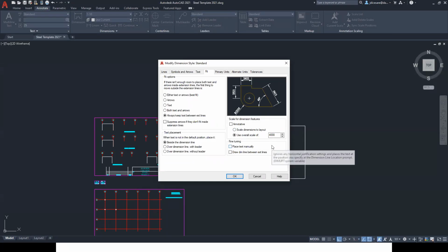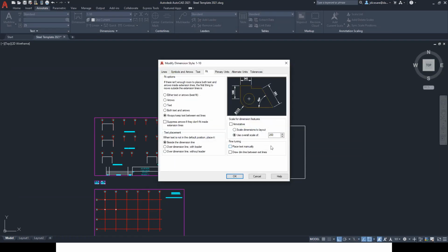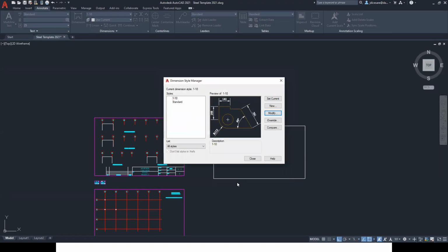So depending on what you're doing. And if you notice, like here, this is for the 1 in 200. And then when I went to 1 to 10, to get always the same arrowheads and everything else, I simply went in here and I did 1/10 of that size. And then all my arrowheads were the right sizes.